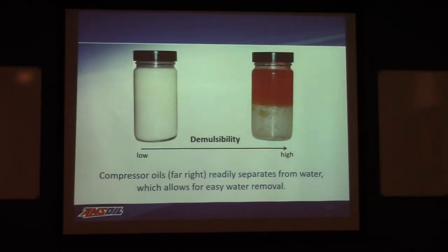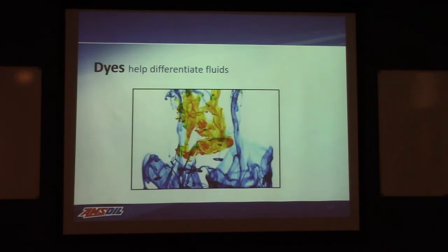And here's an example here. Okay, here's a good one, where the oil, or the water, has been emulsified. It's a good mixture on here. Here, it separates quite rapidly. You can see the two. And obviously, if the oil pump was down in that lower section, the one on the right there, that could be an issue. Could be an issue. Compressors. We want the water to separate very rapidly, so it's going to demulsify quite quickly.